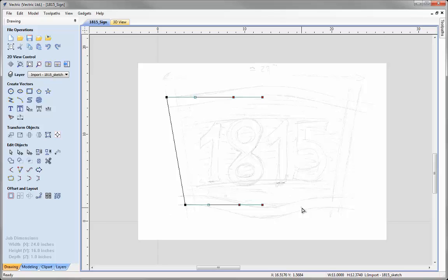However, now I've got the option while in node editing to hit V or H to do vertical or horizontal symmetry. In this case I want vertical symmetry, so I'd hit V on the keyboard. You can see we get this dotted line here, and now if I use the arrow keys and move these up, you'll notice that the top one moves up, but this one moves symmetrically away from the line there. So basically it's just creating mirrored symmetry around it. I'll show you the horizontal one in a moment. So that adds even more flexibility to the already very powerful node editing in the software.